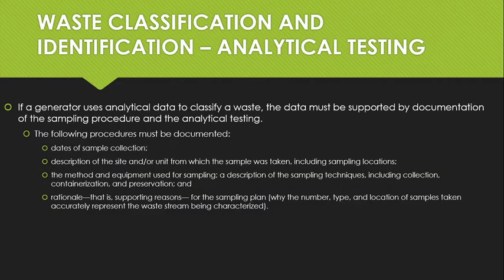So, as you can see, for that profile, I had to use analytical testing. And that's what this next section goes into, is how we're classifying the waste. I had to use analytical testing on that sewage because the landfill requires it. But like I said, for example, if it was diesel and soil, they don't require any testing on that. So we'd be okay just using an SDS and using that process knowledge and just describing the situation and how that waste was generated. But a lot of the times, analytical testing is required, and it really is the most surefire way to classify a waste.